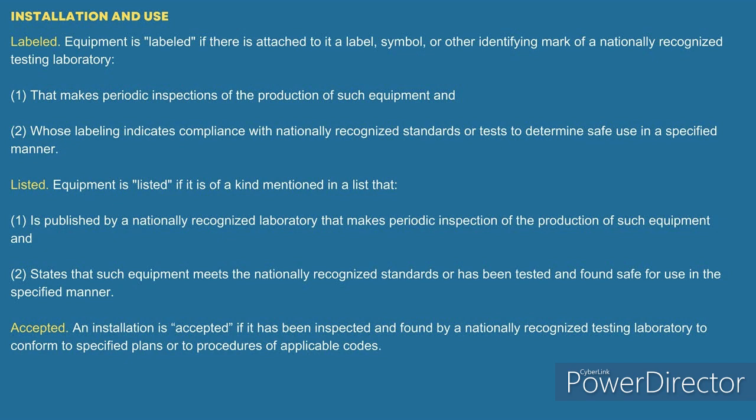I agree. And that's what accepted is, because they are saying it has been inspected and found by a nationally recognized testing laboratory to conform to specified plans or to procedures of applicable codes. So that means they looked at the NEC and everything else out there and determined I don't need GFCI protection. So when you have code-making panel members come in and say, nah, you still have to put it on there, well, tell OSHA that, because they're telling you it doesn't need to be. I agree. See what I'm saying?